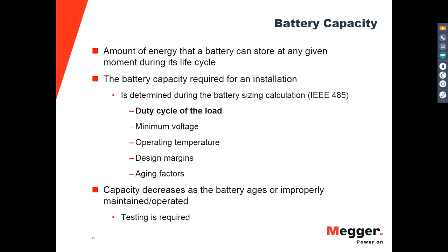Very important in this process is the duty cycle of the load. The designer needs to know how the load is going to behave and how long the battery is expected to support that load in case of a power failure. Also very important is the minimum voltage that the load can work with.